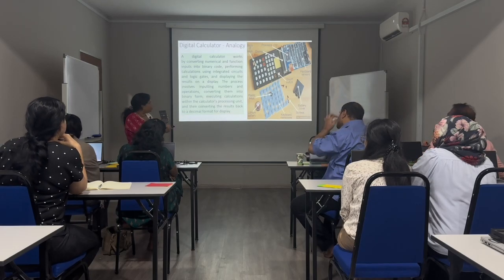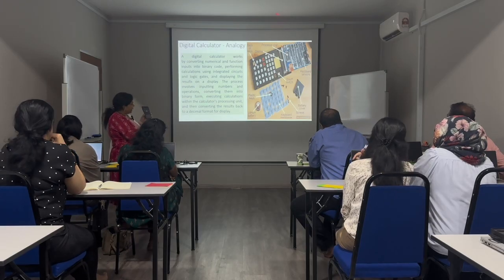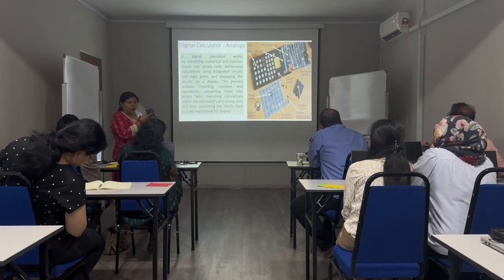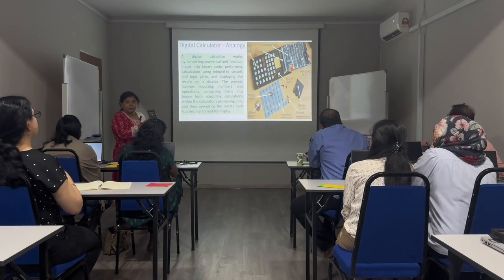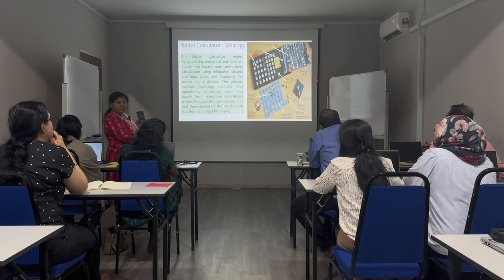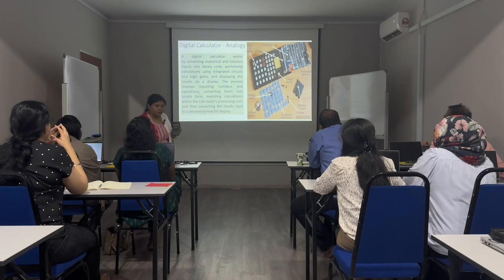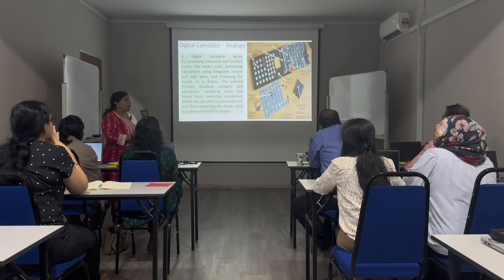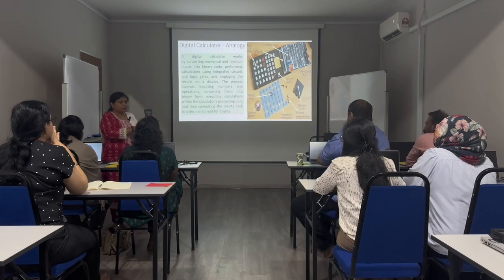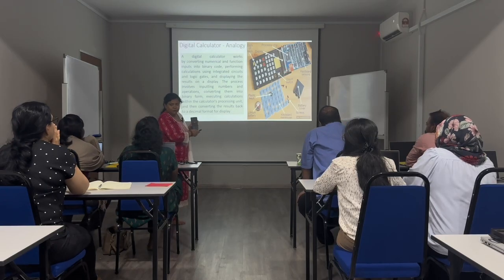That key bounce will be recognized by the key sensor. It checks from which row and which column the key is being pressed. That information is taken by the key sensor, and this sensed data will be encoded. Encoding is the process of converting your analog input into a digital input. This will be converted to ones and zeros, and this information is given to the processor.